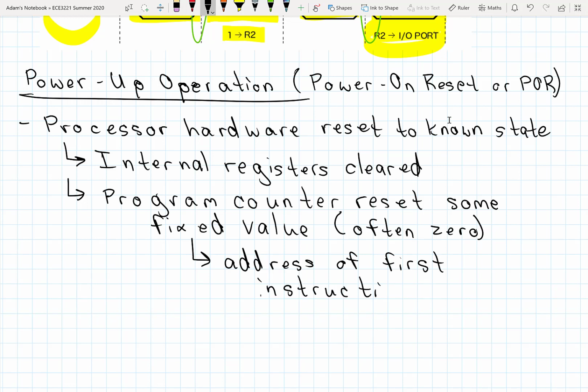Now, next time you're looking at code for the lab, you'll note that although there is an instruction at address 0, that first instruction is often a branch instruction to some other location in memory. So your code doesn't tend to all reside in consecutive memory locations starting from 0. There's just some branch, located at address 0, to where the code actually exists.